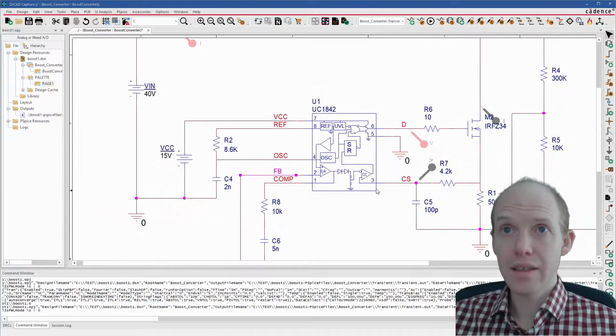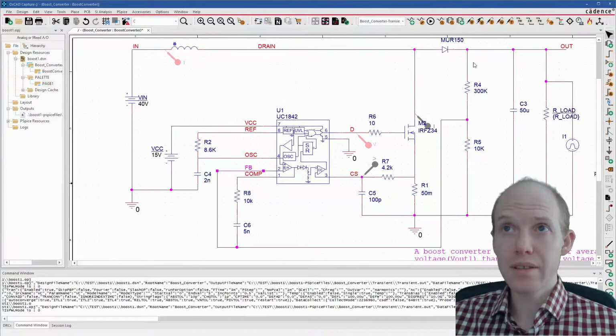And then you could linearize this whole thing at once, or you can do it in 2 blocks. So sometimes I like to do 2 blocks where first you just linearize this chip to a duty cycle, and then after that you have another block that converts the duty cycle that is now represented as a DC voltage between 0 and 1 instead of an actual pulsed duty cycle.